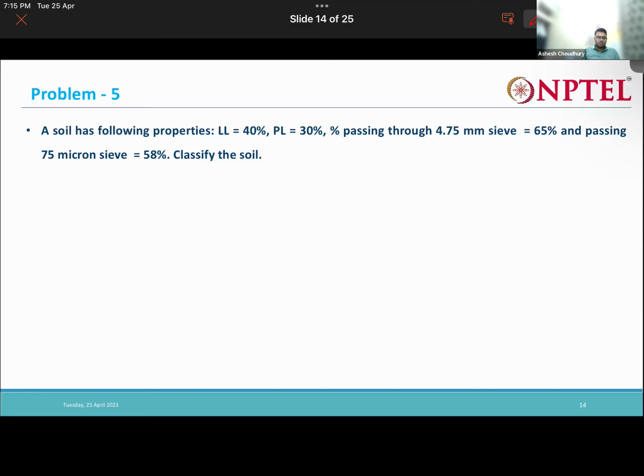Right. So how do we classify the soil? First we have to sieve the soil, right? So sieving is the process. There are wet sieve analysis and dry sieve analysis. What we need to do is the dry sieve first, and if there is a considerable amount of clay fraction, then we need to do the wet sieve analysis too, followed by our hydrometer analysis, right?